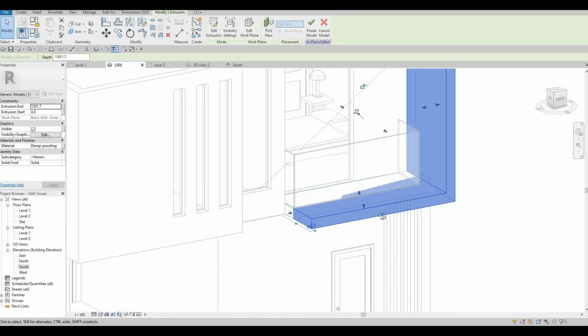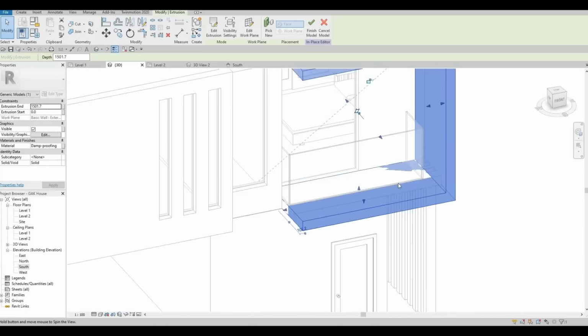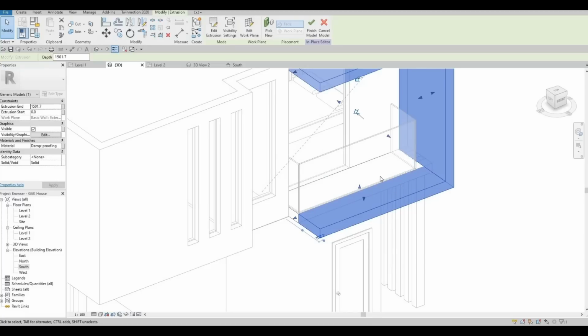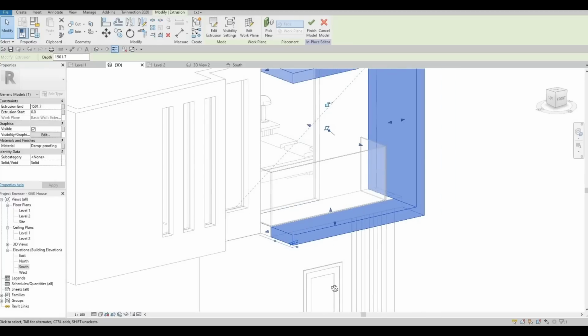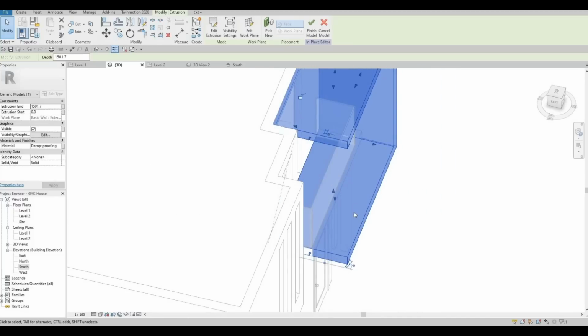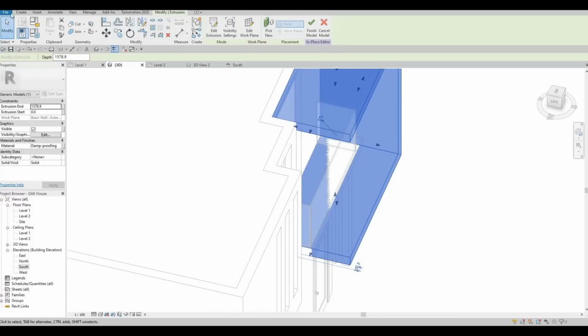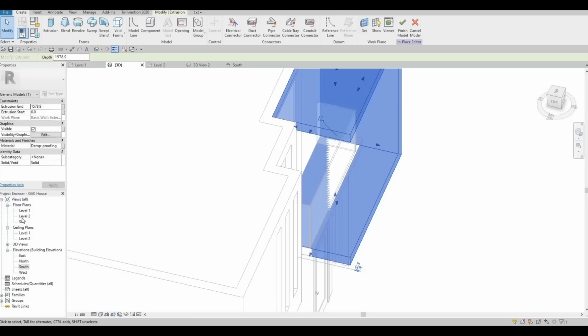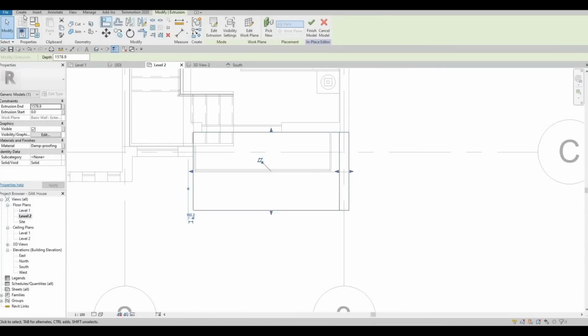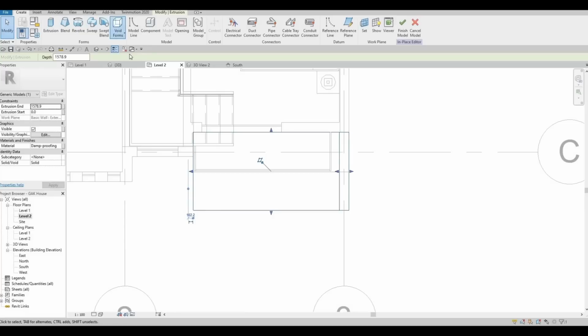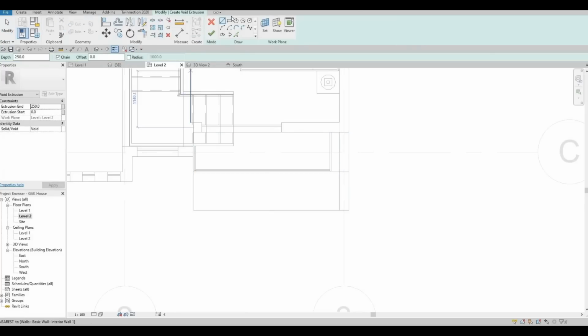I might edit the floor here. It's because it's creating those flashing light. It's because it's overlapping. So I'm just gonna edit that later. I'm gonna move it like that. And we will need to create a void. So we could go to level 2 and create, and then void form, and then void extrusion.